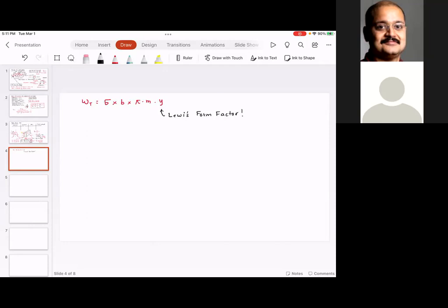And the reason for that is when you perform the hand calculations, the basic assumption is that plane sections remain plane. The calculations are in 2 dimensions, but the actual loading conditions are 3 dimensions. The plane sections do not remain plane. For example, if you look at the gear, the first level of assumption is the cross section is uniform. That is how we derive the beam strength equation. But that is not true because gear has the curvature, so the cross section changes.